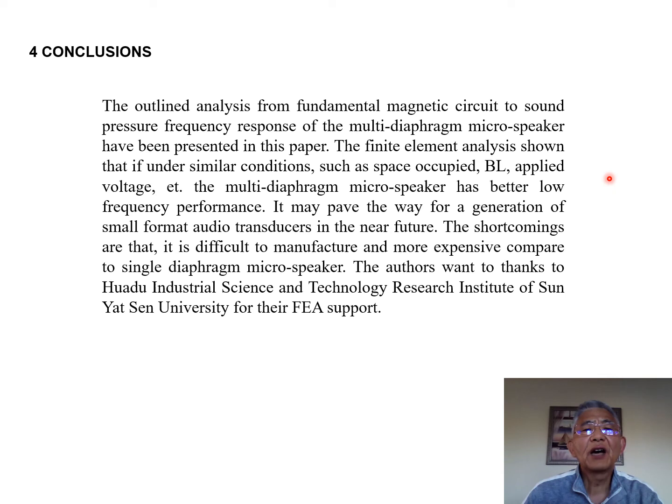Conclusion: the outlined analysis from fundamental magnetic circuit to sound pressure frequency response of the multiple diaphragm micro speaker has been presented in this paper. The following finite element analysis showed that under similar conditions such as space occupied, BL, applied voltage, etc., the multiple diaphragm micro speaker has better low frequency performance. It may pave the way for a generation of small format audio transducers in the near future.